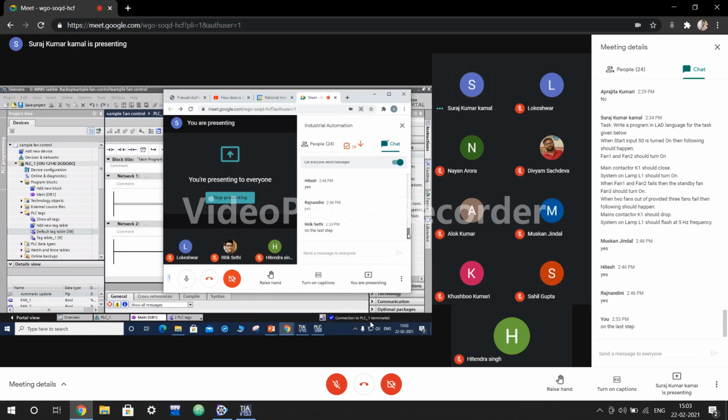Acha, you have already given a reset to the contactor. Yeah, this can work. Ritik, it is correct. What you have done is that you have directly added this to your reset contactor. Yeah, this is correct. This will also work, Ritik. So your conditions are fulfilled when your switch S0 is open and